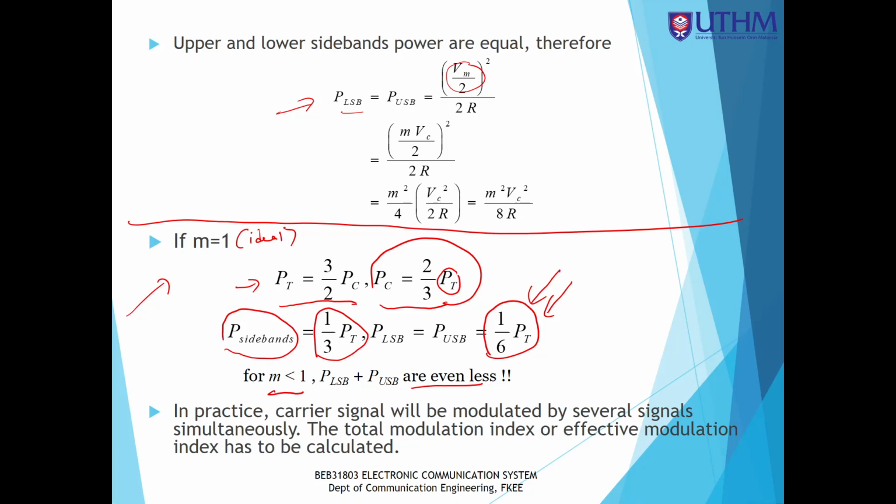which is good. Okay, one of the methods to increase the efficiency is to do the multiplexing process. We use multiple frequency inputs. Okay, so this answers the previous statement about the disadvantage of double sideband full carrier.